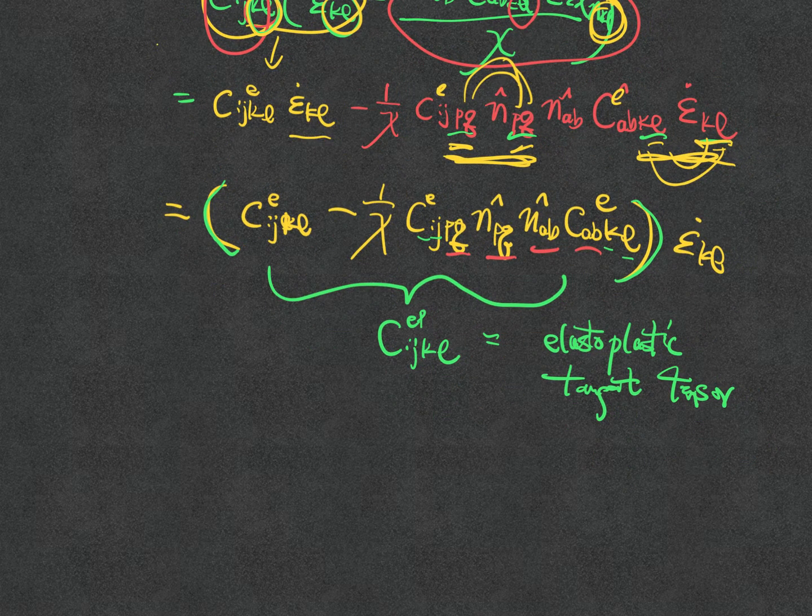So this C^EP could be an indicator that gives you a sense of whether you have unstable deformation of the material, because it's a function directly related to the total strain rate. From the algorithm part, you have to compute the C^EP in order to put anything into the finite element, because the finite element code doesn't understand what is elastic strain and total strain. You get the strain from computing the displacement. From the displacement of the node, you apply the B matrix, you get the strain, and that strain compared to the previous strain gives you the strain rate, and you need to compute the stress.